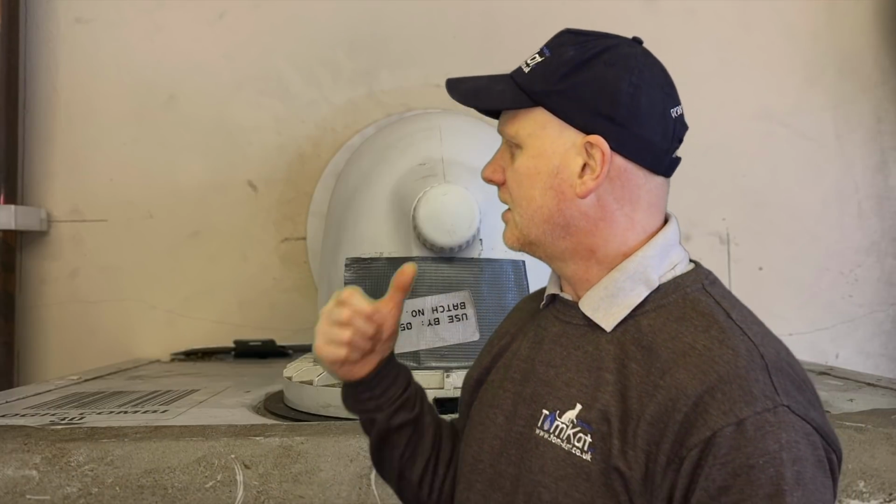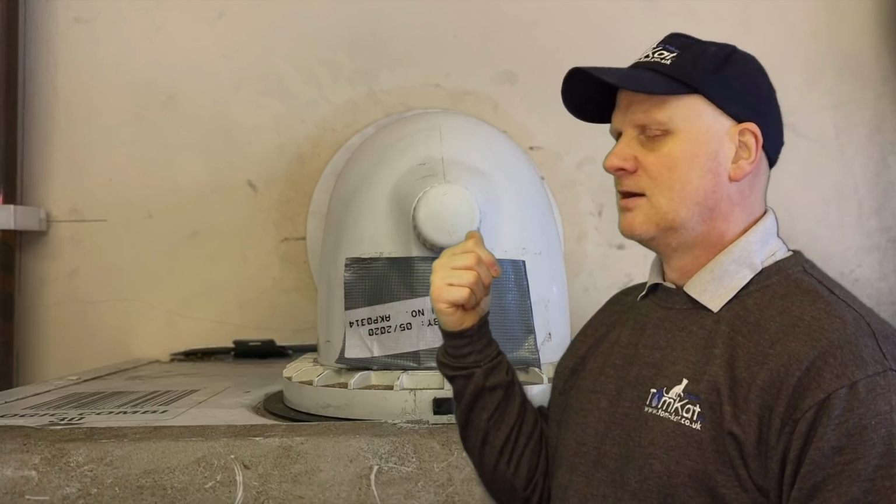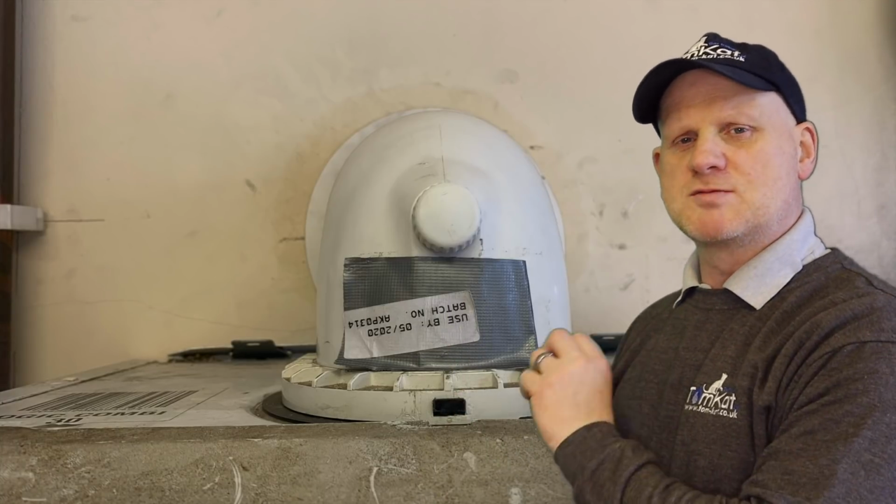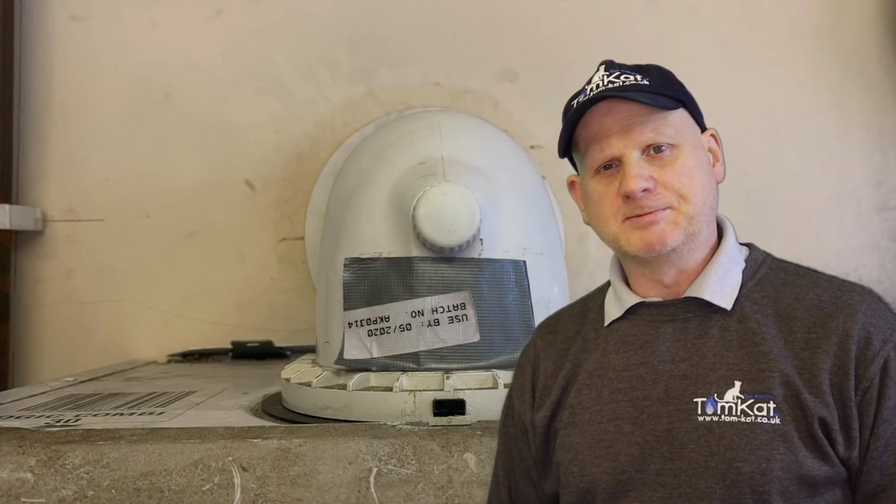Now, another common fault we seem to be seeing quite a lot now when we go out to service boilers or repair boilers is this one, where either the air inlet test point or the products of combustion out test point is either missing or broken. Now then, take this situation here where this is the air inlet, not the products of combustion going out, and the bung's missing, so somebody's put tape over it.